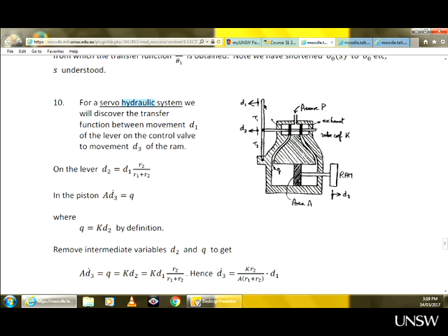It's a human operator that moves this lever to the left. As a result, because the pivoting point is here, the whole lever will move to the left, therefore this point as well. As you move this point to the left, that's how you move this piston. That's how you allow high-pressure fluid down into the actuator, into the cylinder.